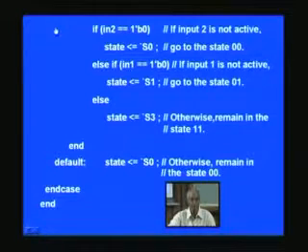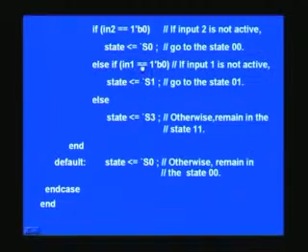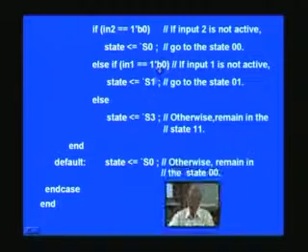And then we started with case, so there must be an end case here, and we also started begin after always, so this end accounts for that. For example, let us say in2 is 1 here and in1 is also 1, both are 1, so it should naturally take you to S3, right?